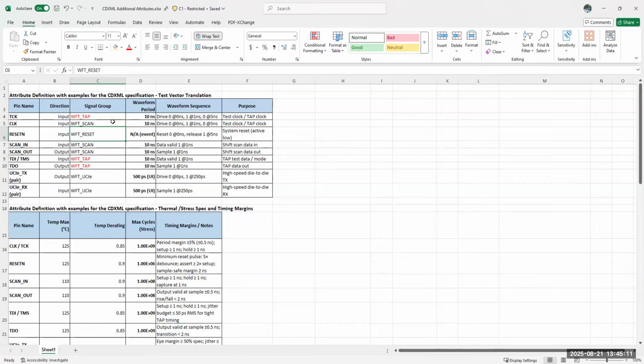Yeah. Is the reset for test different than the functional reset, or is it the same reset pin? Yeah, this is a shared functional and test reset. You can assume that way. So it's one reset pin that will reset the entire device. You don't expect to have multiple resets, right?